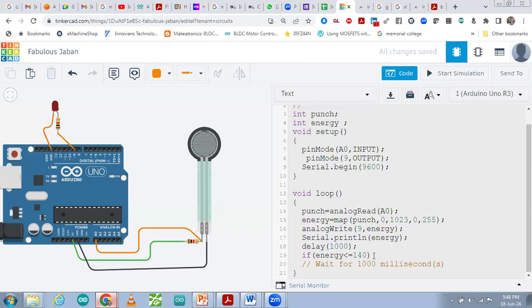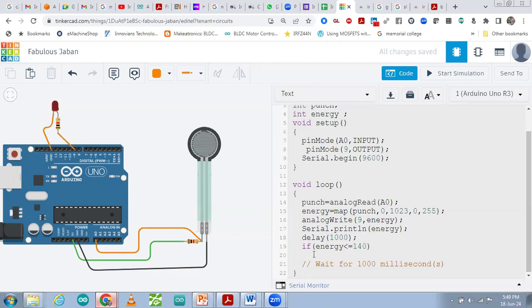So in this condition, what you want to print on the serial monitor, you can print with Serial.print. Whenever you have to print only the value or only the name or some keywords, you can use a double quote, and I'm going to print 100% over here. Anything you can print over there. So 100% I'm just writing it.